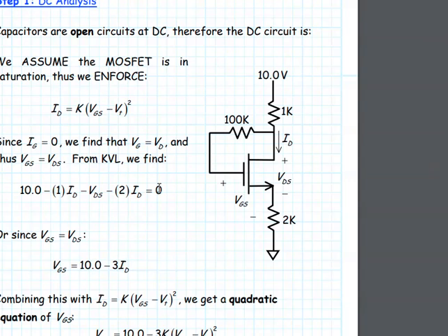Also here, since the drain and the source are connected to each other using this resistor, and this resistor we know is not drawing any current, the voltage here and here are equal. So the VD equals VG. So VDS equals VGS. Interesting, right?